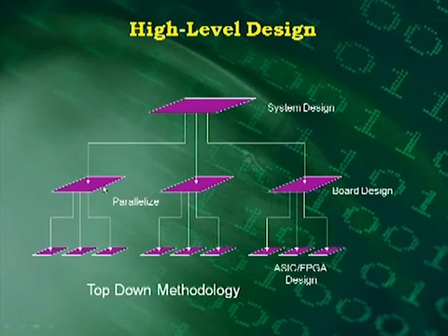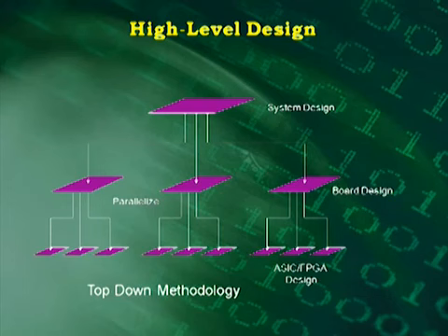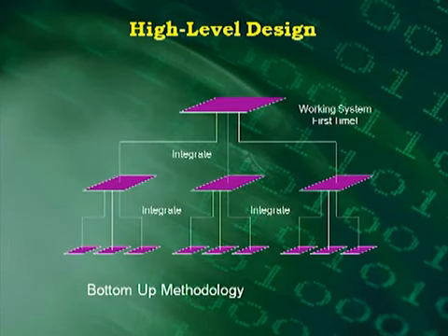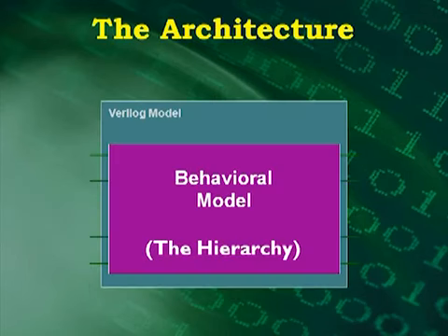Such as in the HP SDR project. We've got several boards in there. You can use Verilog to help you not only design or model those boards and maybe FPGAs, but to model and simulate the whole overall design if you wanted to. Or you could divide it to do a bottom-up where maybe you have individuals working on little subsections of the design, you integrate it, you work back up, or maybe you work it from both directions. But the goal is you want to have a working system the first time.